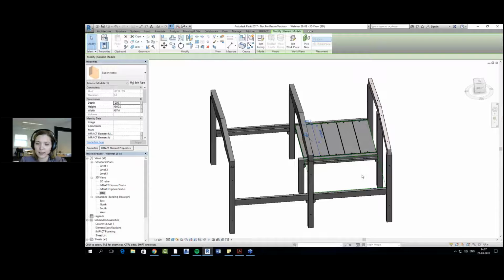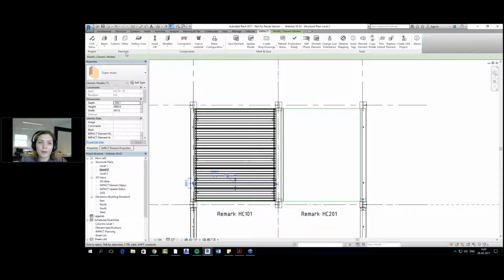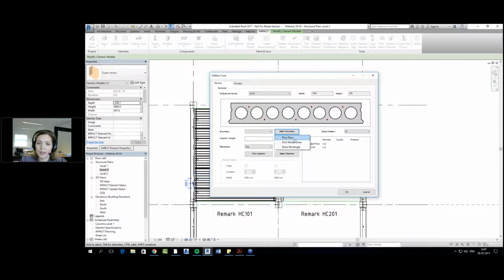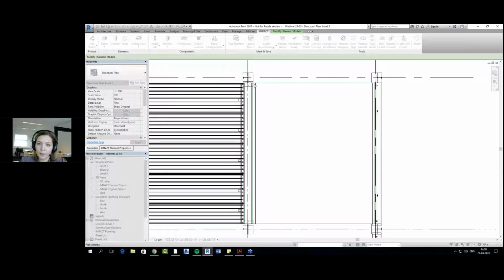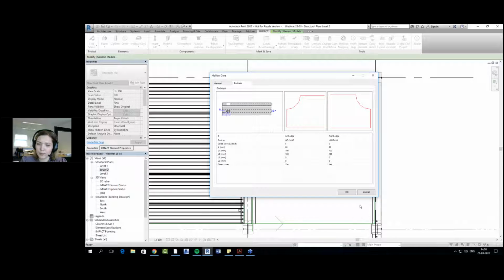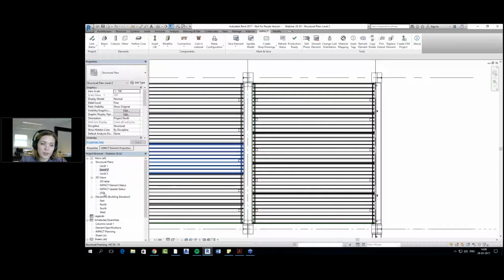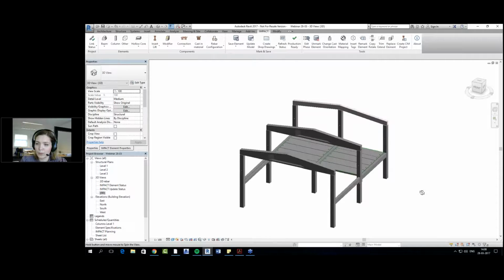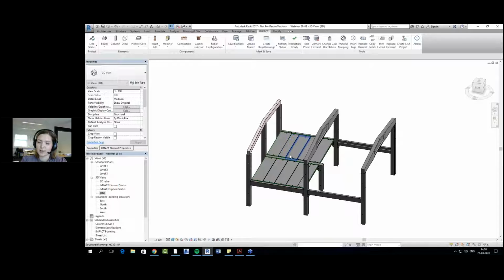let's draw another part of the hollow cores on the other side, by using a slightly different method. So let's go to Impact Hollow Core and say draw some shape. So I will be following the model lines, but drawing with the Impact function. Again, placement top, and so on. All the settings seem to be the same. I say OK. So this was an even faster way to draw hollow cores, and they mostly look the same, except some settings like partial slab, and so on.